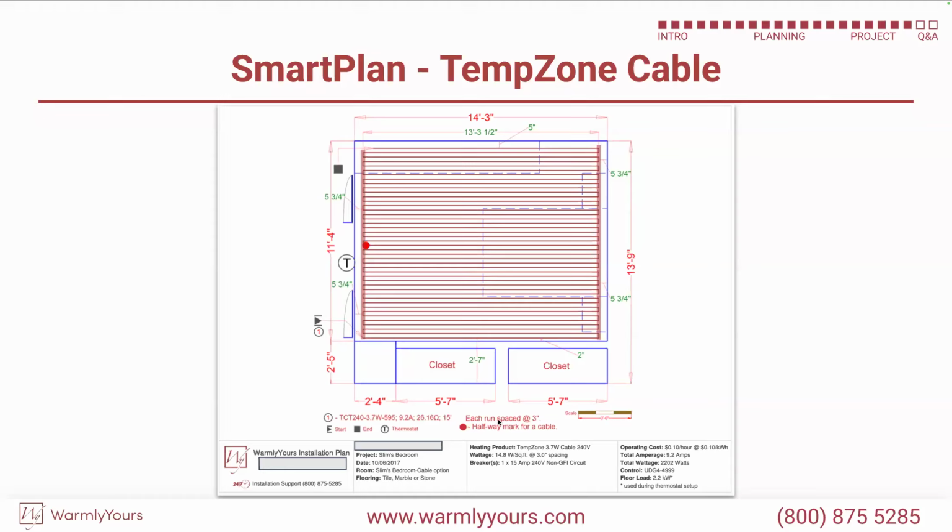Now, these cable fixing strips have loops every 1 inch, so you can do your spacing correctly. If you're getting to the space here where you're using up too much, you're probably at 2 inch spacing, which is a big problem because you can't do 2 inch spacing. If your red dot has moved all the way over here, it means you might have been doing 4 studs instead of 3. So you're doing 4 inch spacing instead of 3. So you're going to end up with way too much cable.